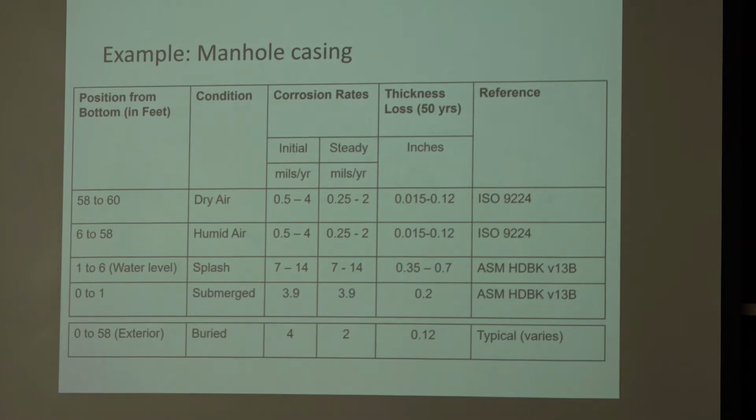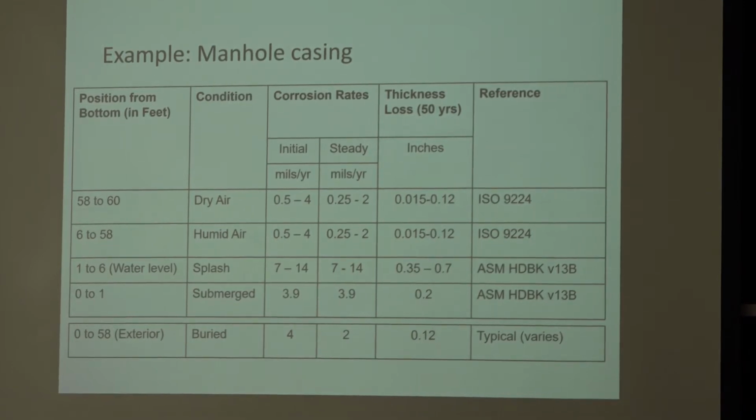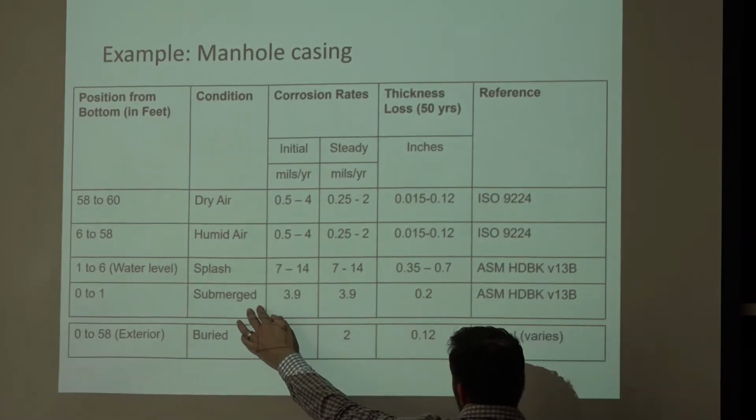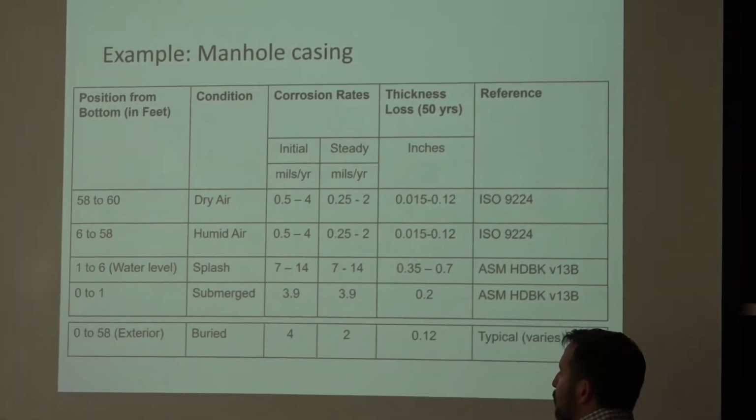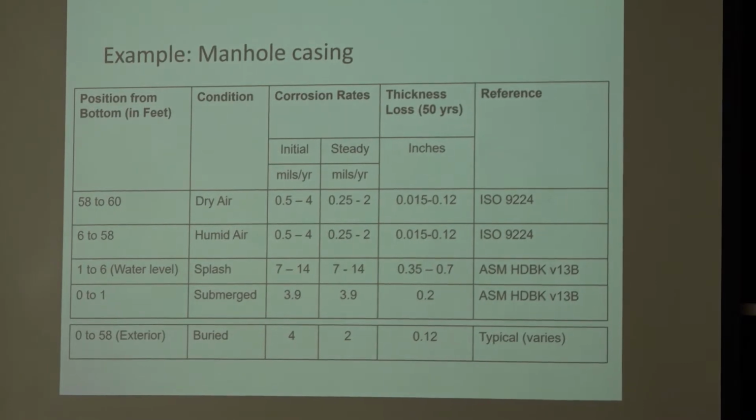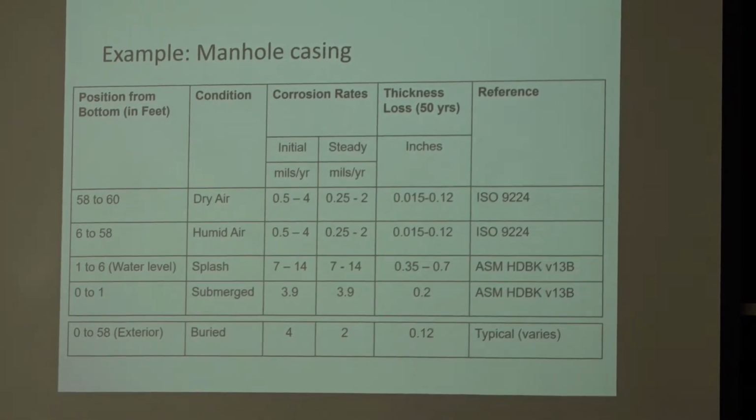You could put galvanizing, but it has a pretty substantial cost associated with it. And in some cases, the galvanizing is not as effective in soil. So you start thinking about, okay, what happens if the piece of steel is not protected against corrosion? The one number that I think would be good for you to keep in mind is the submerged condition. So in potable water, if you have steel that's corroding, you lose approximately 0.004 of an inch or 100 micrometers per year of exposure.